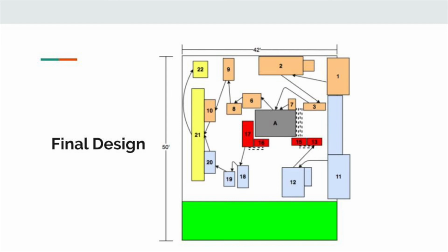After analyzing the data and discussing with the company, the team created this final cell design. This design incorporates aspects of our top 3 alternative designs that together address all the project objectives. In this design, the cells rotated 90 degrees, moving where the raw materials and finished products are dropped off and picked up. We also brainstormed a new way of handling parts, through the use of roller tracks between certain workstations to reduce the number of times the operator used the overhead hoist. From our line balancing task analysis, we found that a new machine can be added to the cell to help balance the workload between operators.